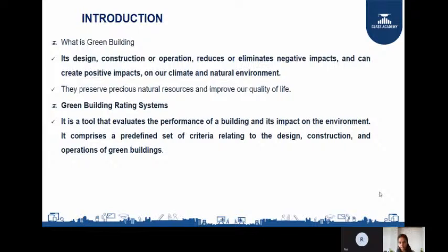Say we have 50 layers or 80 layers of coating. From those 50 or 80 layers, in fourth generation, one layer will be of silver. In fifth generation, it is a double silver product, so two layers will be of silver. And sixth generation is a triple silver product. You will have three layers of silver, and because of that you are getting a higher performance here.